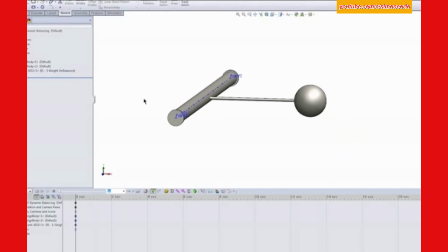So when I click on one of these tabs, this is very similar to working with Excel. I have a couple of options here. If you're using SOLIDWORKS Standard or SOLIDWORKS Professional, you would have access to animation and basic motion. As soon as we're using SOLIDWORKS Premium or either of the simulation professional or premium packages, we have an option for turning on motion analysis.